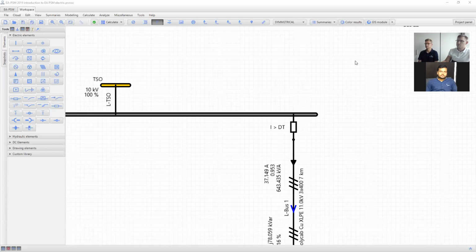Actually, you need to only specify a network from the substation to the solar power plant. So in this case, like up to 50 buses would be enough. Of course, if you want to create a distribution network in that town, so you might need much more buses, but always it depends on how detailed analysis you have to do.